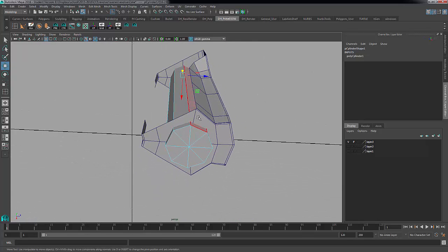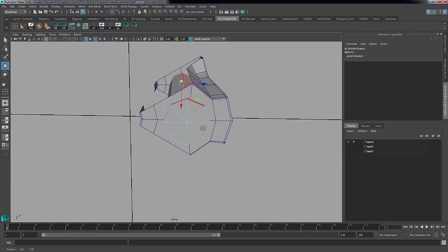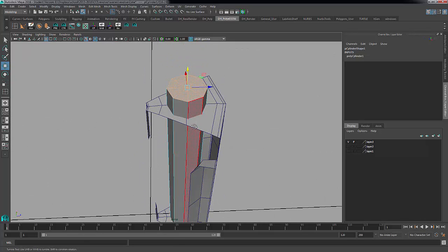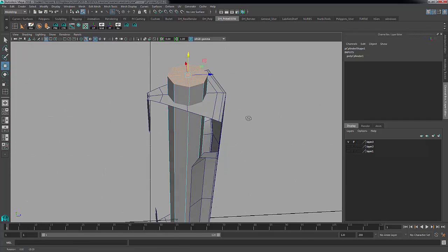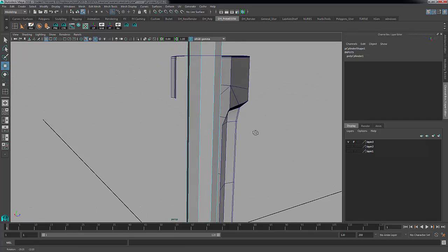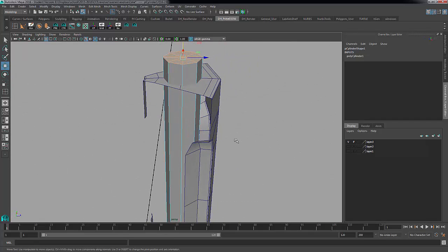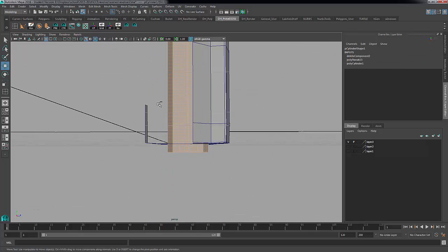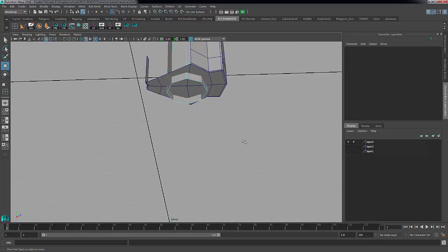It looks like it's a little bit off down here, but that can be fixed pretty easily. It's a little bit off up here as well, but I think I'm good for this Boolean. So let's take those faces and delete them. I'll select them all and then Control-deselect those, and I'll delete those.